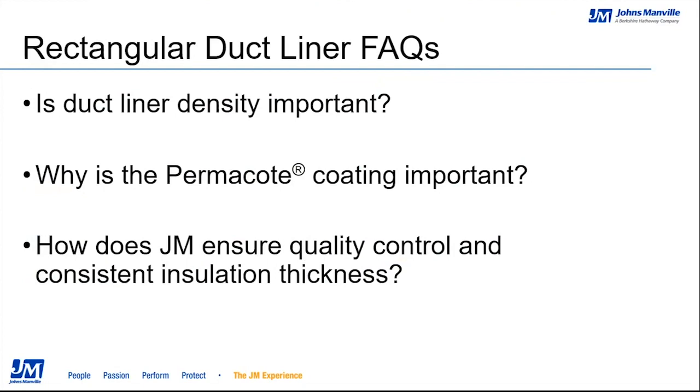And the fact of the matter is, a lot of the master specs that are out there don't get updated. Technology evolves. Think about your phone. The same phone that you had in 2000 is not the same phone that you had in 2019. Things evolve, technology changes. We found ways, as the fiberglass industry, to find better solutions to give you better R values without tying it to density. So if you're seeing density specs or you're still writing density-driven specs, I would encourage you to look for our specification or update and find a better solution for what you're looking for there.